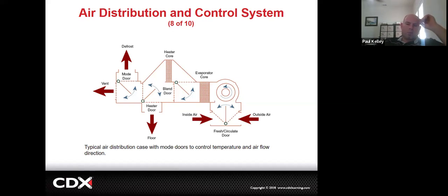I've also noticed if you put it on recirculate, a lot of times they're worried about this thing getting wet and kind of nasty. So if you put it on recirculate, rather than risk building up mold with your wet, moist air, it'll run the AC. It'll actually kick the compressor on and cool this down, and that'll keep it from getting musty and smelling and getting growth on it. So they'll run this evaporator core on and off. They may run the AC, but they're always going to have air going through it to keep that thing kind of clean. Make sense?